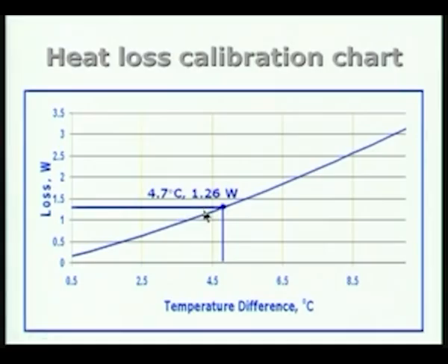If you remember, the uncertainty in the value of measured q is about plus or minus 0.75 watts, and you can see that the loss here is even larger than the uncertainty which we have got in the problem. Therefore, it is essential that the loss, which is about 1.26 watt in this particular case, is taken into account, because if you do not do that, you will incur a very large error in the value of k which is determined, even though the k itself has got an error of about 6.6% because of the uncertainties in the quantities that are measured.